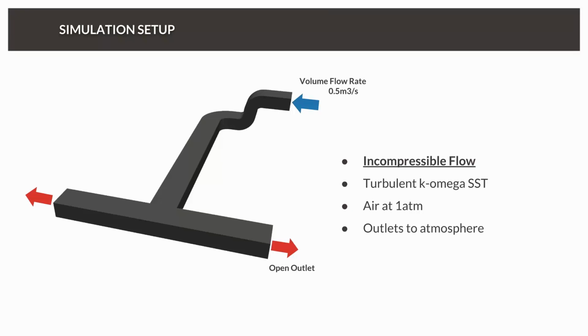Whenever we have a flow separation, the global flow physics massively changes, and when the manufacturer calculated and measured the loss factors for the single parts, it was all based on having a flow which is not separated. This is just an example which shows when and why the analytic models can fail. And whenever they fail, CFD is the right tool to get the information you need.